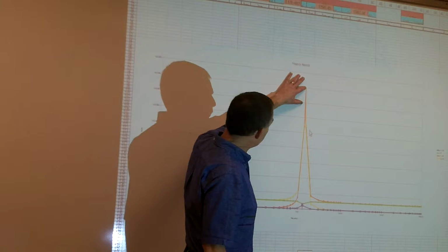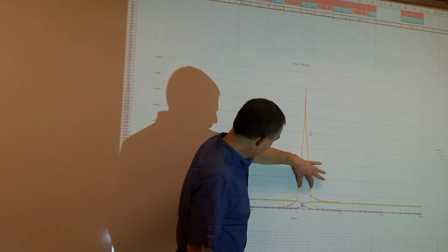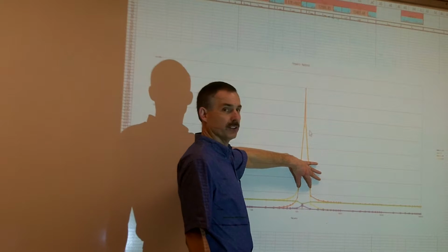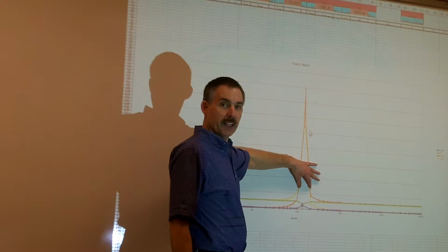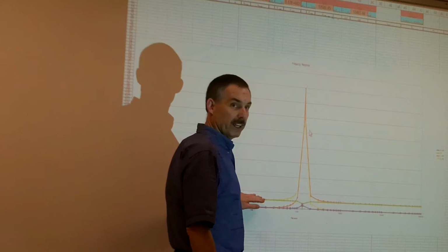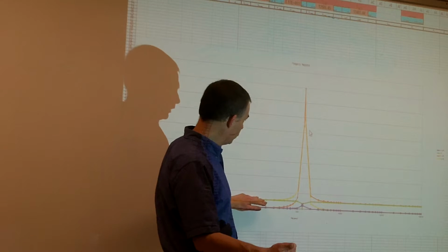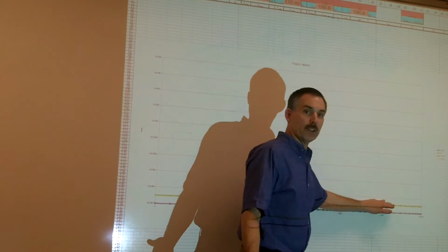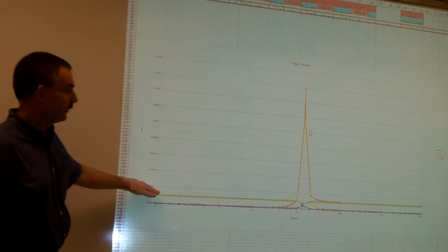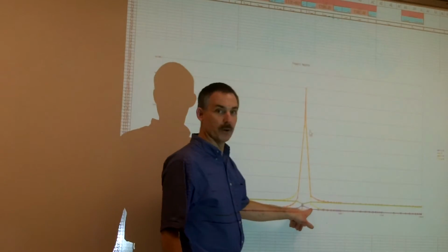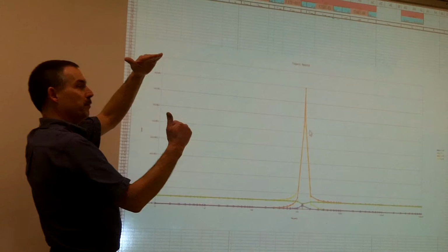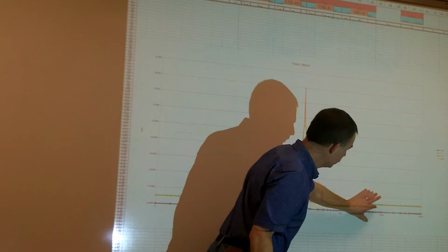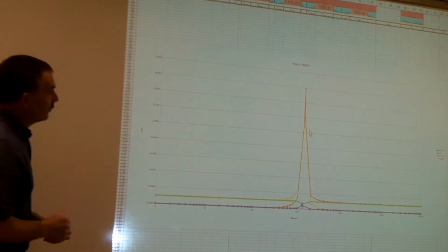If I didn't have those 3 data points in there, I've only got, what did we calculate, 816 hertz for our bandwidth, right? So if I don't plot that resonating frequency, my bandwidth, my upper and lower frequency cutoffs, I can miss that totally, completely in my spreadsheet. I wouldn't even see this thing spike because it only happens so quick. So if I got a number above it and a number below it, outside that range, all I'm going to see is this, because I'm going to miss those points.